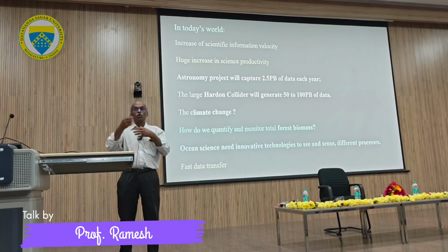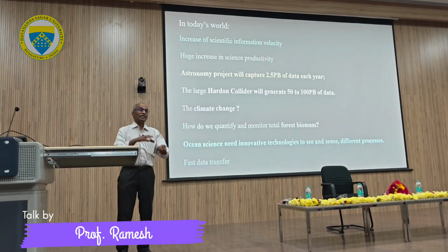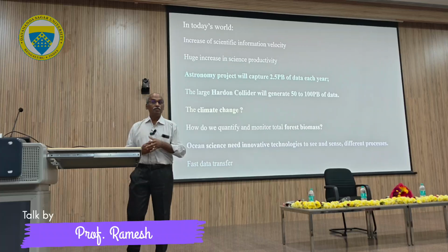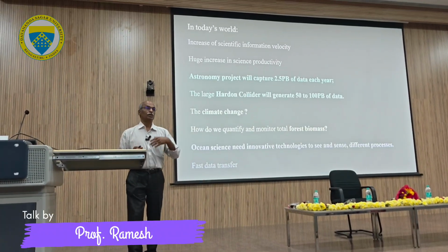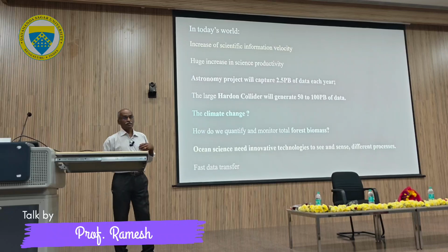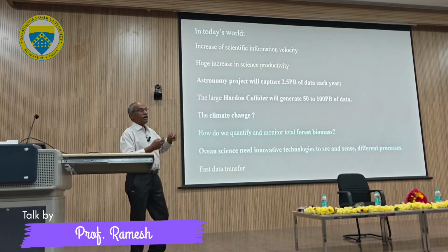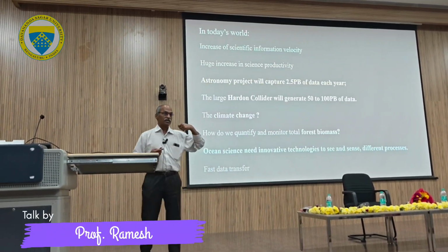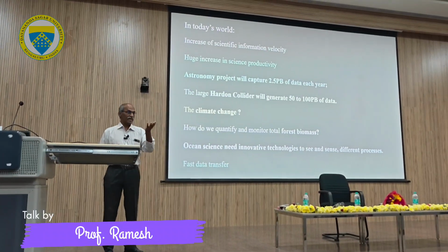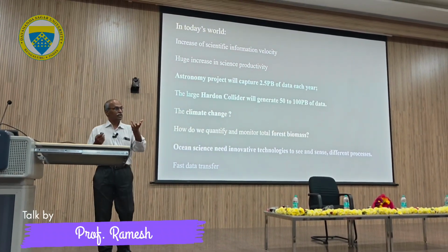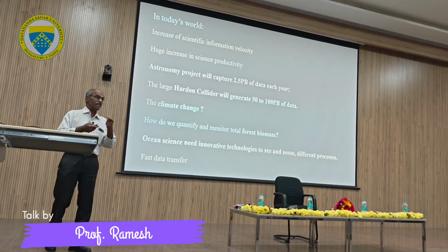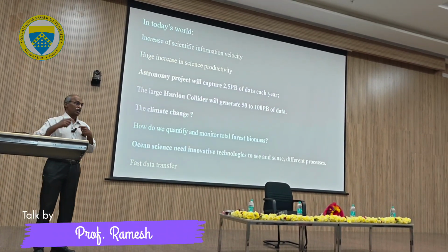All the glasses will go to the crystalline state, but the property difference between these two states is not appreciable in many of the other oxide glasses or metallic glasses. But chalcogenide glasses have a huge property difference, like 1000 ohms. If you take refractive index, it's about 30%. If you take reflectivity, it's about 30 to 40% difference. So these are the properties people exploit for storing information, right?